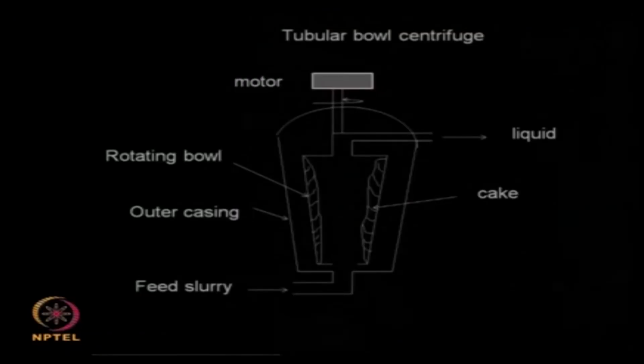or I can say if I have 10% impurity and I add so many 1000 liters of washing liquid, how much will be the reduction in the impurity from 10% to what value. So I can use these two relationships, they are very simple relationships, to calculate the impurity profile depending upon the amount of washing liquid I am using and depending upon the physicochemical properties of the impurity as well as the cake. We will look at some problems in the next class.